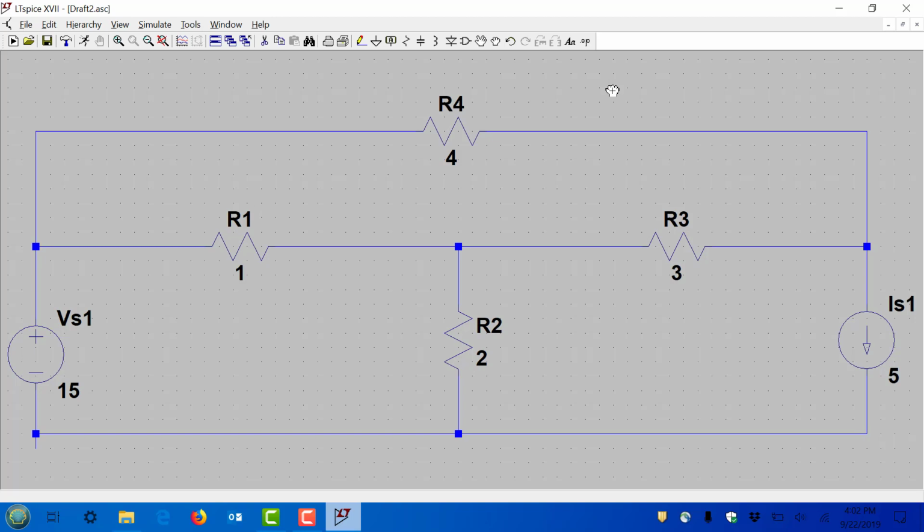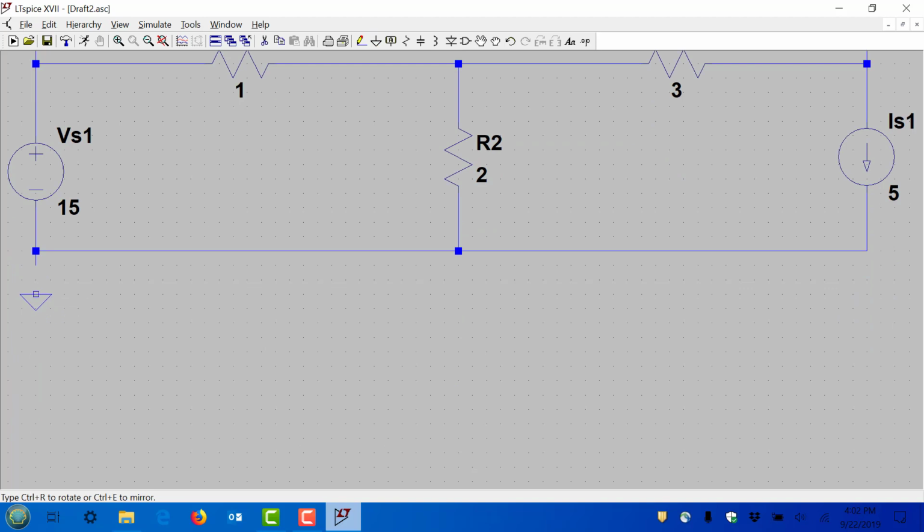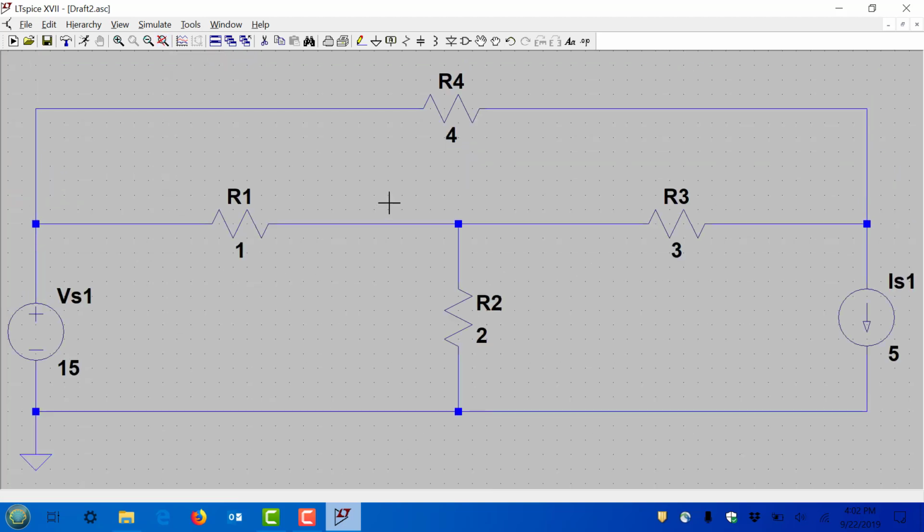But now, as it stands, we've pretty much wired the circuit, except that, as I said, the circuit simulation runs based on nodal analysis, and we know that nodal analysis requires a ground symbol. So we have to declare one of the nodes to be the 0-volt node or the reference node. And so here is the voltage ground symbol. We simply pick that, and you can place it anywhere you like. Maybe you place it somewhere down here, and then wire it to the top like this. And now we pretty much have a complete circuit. It's ready to be analyzed.